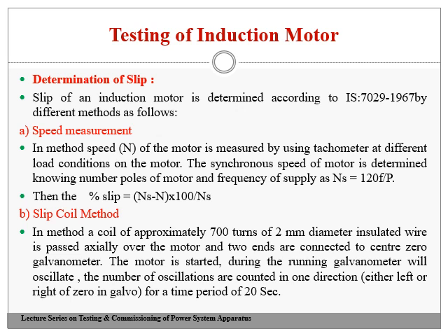In this case, first of all, we are supposed to find out the synchronous speed at which the induction motor will be operating. The synchronous speed is given by the equation 120 F by P, where F is the frequency of the supply and P is the number of poles. Then, with the help of a load test or any other test, we can determine the speed at which the induction motor rotates, which is taken as the value of N. At any load condition it will be operating at a specific speed, and that will be taken as N.